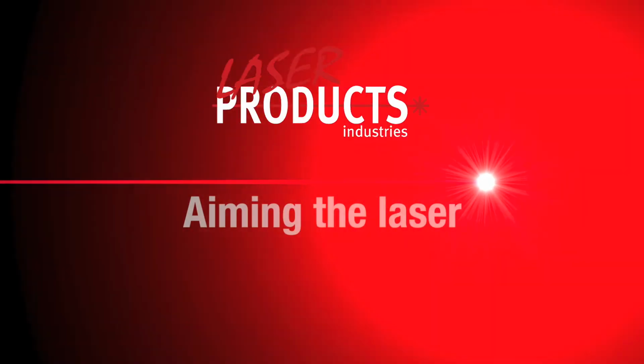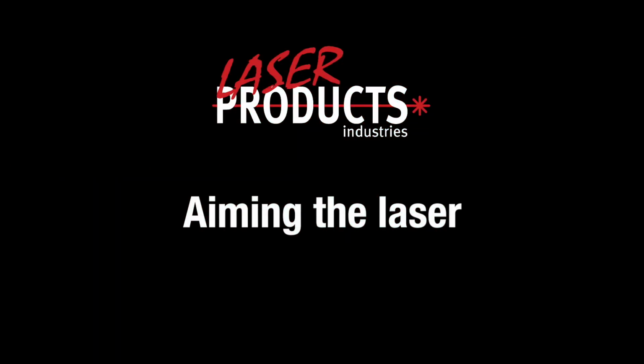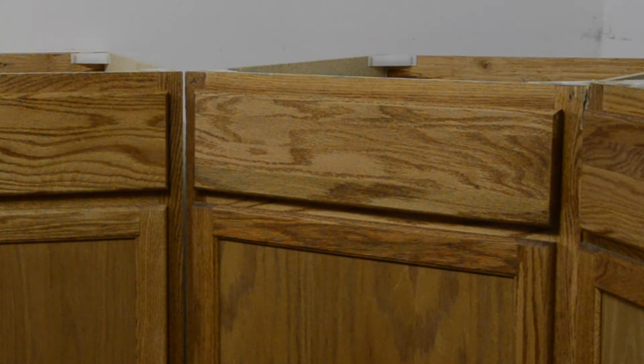In this video, we will discuss best practices for aiming the laser when taking measurements. Measure cabinet runs about 1 to 2 inches away from each intersection or change of cabinet direction. As a general rule of thumb, measure points spread out as far as possible on each respective cabinet run to produce the best results.